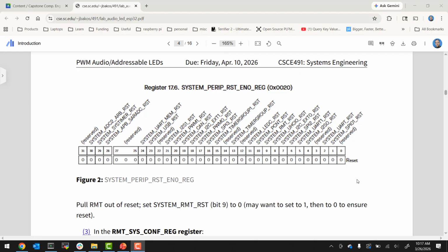Okay, but these are pretty simple. They're basically just a global register. The complicated part for me is figuring out what the address of these guys are. So I mentioned that there's a read reg and a write reg macro you can use to read and write these addresses. The problem is that when you look in the manual, these addresses are given as relative to the base address for different base addresses.